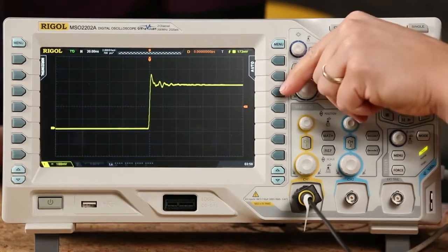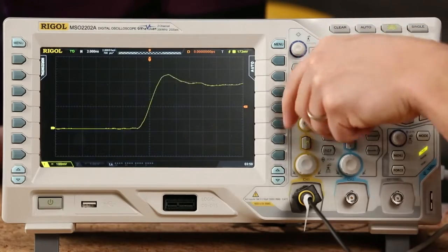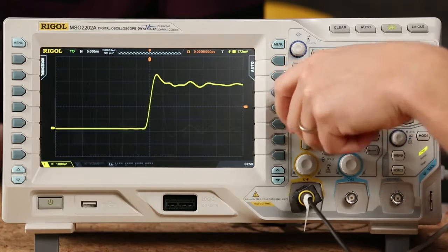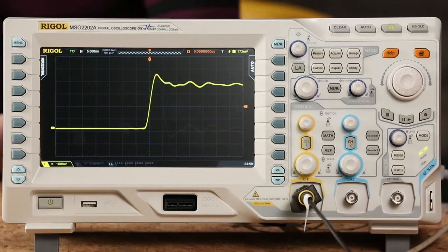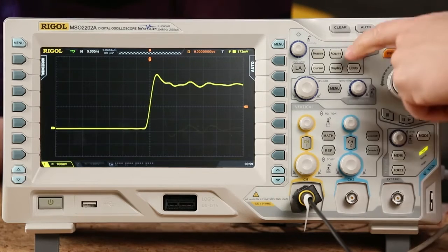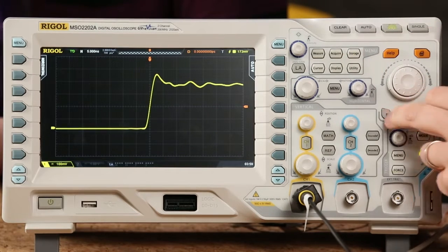So the first thing I like to do is kind of zoom in on that guy. Yeah. And then we can see, at about 5 nanoseconds per division, a clear little drop out there. So what do we want to do about that? Fix it. Well, we're definitely going to fix it, but first we want to analyze it a little deeper, right? So let's go ahead and we're going to